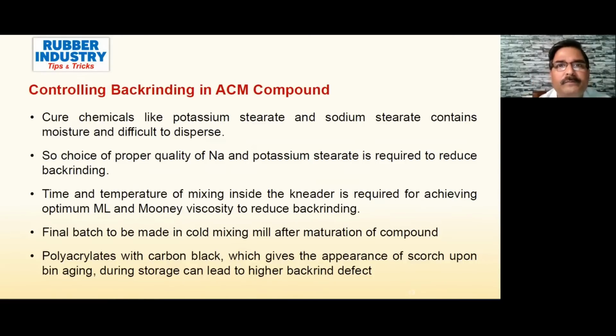Time and temperature of mixing inside the kneader are required for achieving optimum ML and Mooney viscosity to reduce backrinding. Mixing of ACM rubber is very important to control Mooney viscosity and minimum torque values. Master batch is advisable to be mixed in a kneader. The time of mixing and dump temperature should be standardized. The master batch needs to be cooled down, and final mixing should be done cold in a two-roll mixing mill.